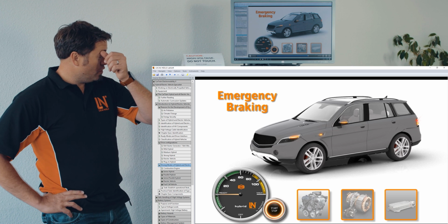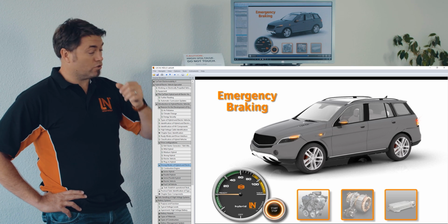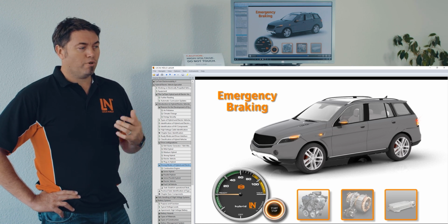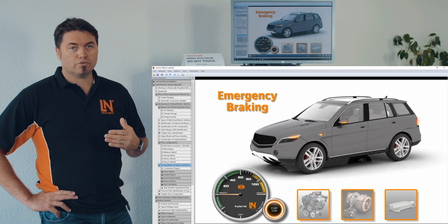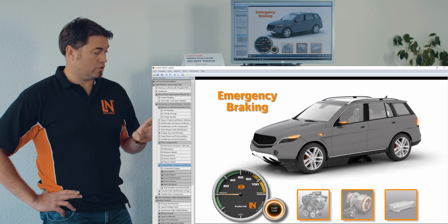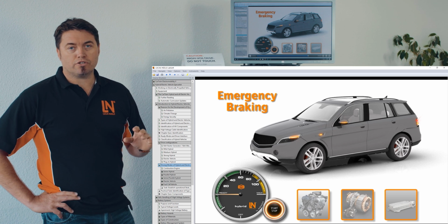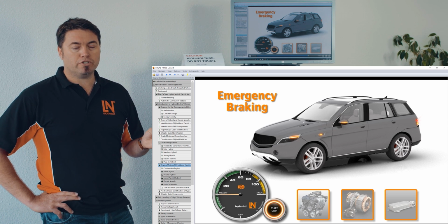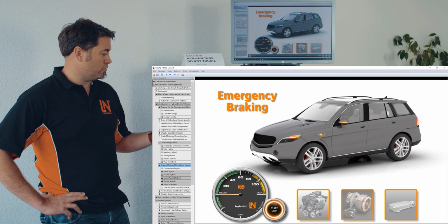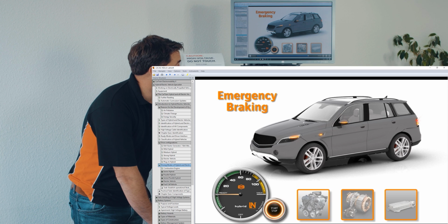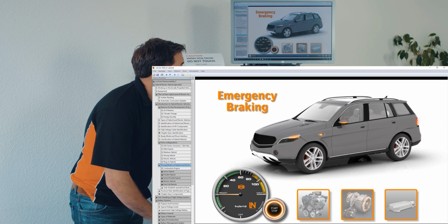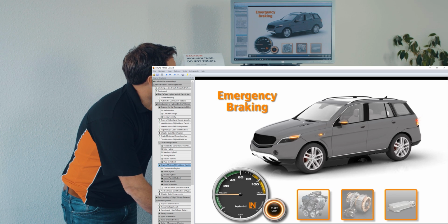So that depends also on various things. Hydraulic braking can occur when the battery is full. So if the battery is full, the system will say, hey look, we can't use the generator, there's nowhere for this energy to go, so it'll switch to hydraulic braking, obviously slowing down the vehicle in that way.